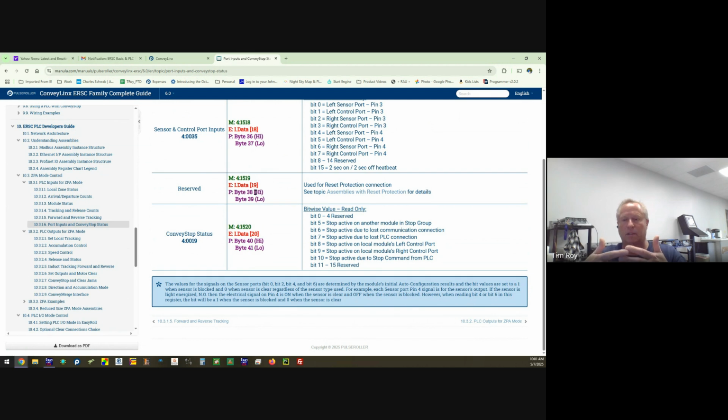The problem is the card works on a change of state. And since the PLC wrote accumulate while the card was still starting up, the card did not see the accumulate bit. It has a load and it released. Well, the taping equipment downstream wasn't ready yet. It was still going through its startup cycle. And we were jamming it and causing issues and problems.